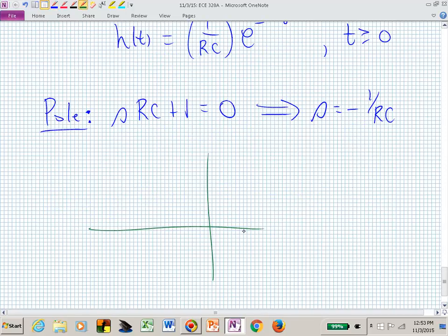Now, not only do you see that circuit, but you should start to see poles and zeros populating in the S-plane, or X's and O's on this S-domain diagram. Where are my zeros? Do I need to draw any open circles? No, I didn't have any finite zeros. What about poles, X's? I just had the one, and that was at minus 1 over RC.